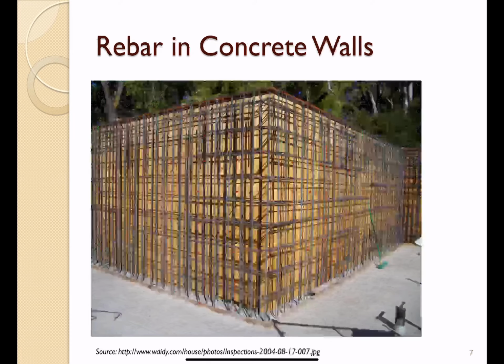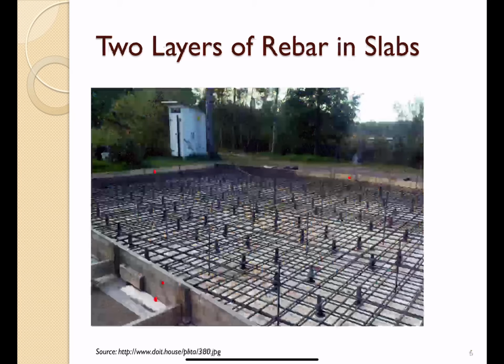Or, you can see that one here, the yellow wooden part in there, that is basically the formwork. After the concrete gains strength, we can remove that formwork, and it is measured by the square foot contact area. So regardless of how you set it up, we only count the contact with the concrete.